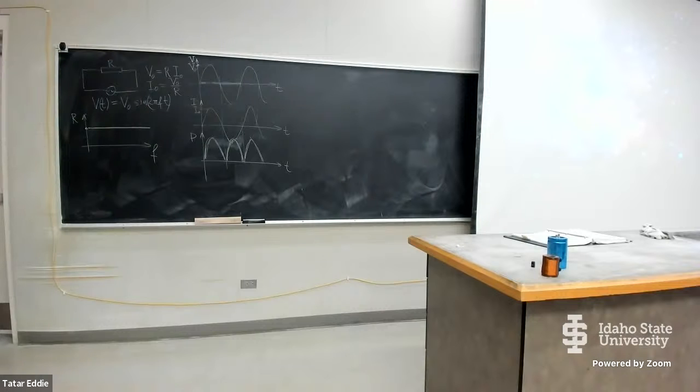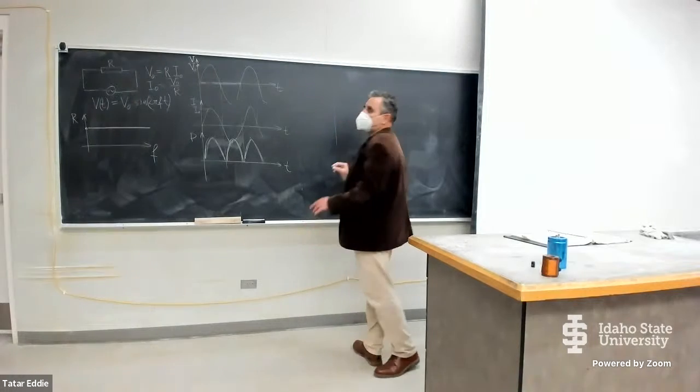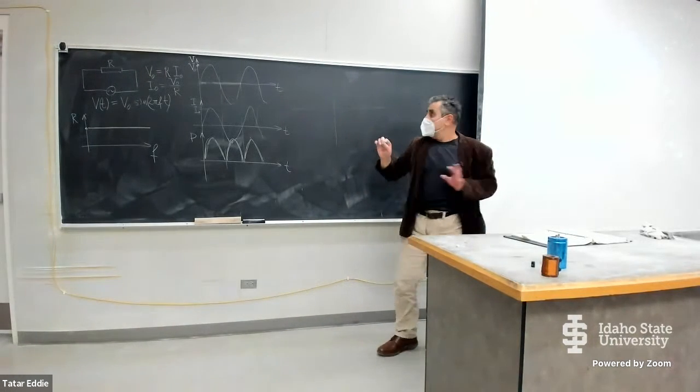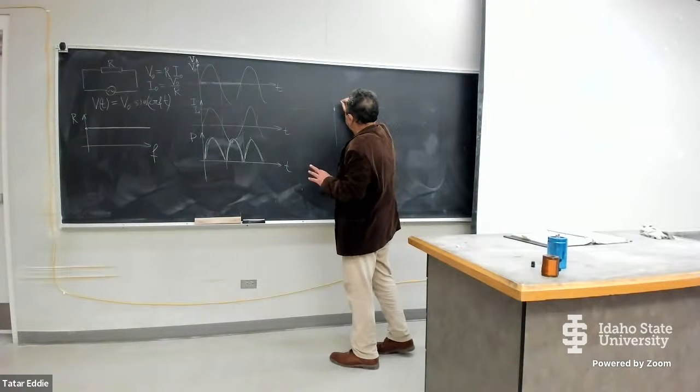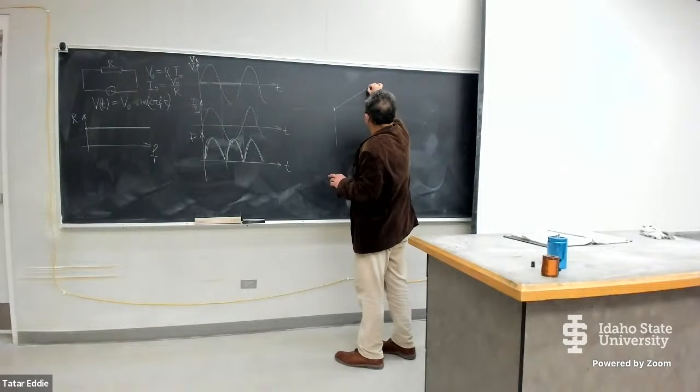And now let's introduce another way of looking at this diagram. Let's represent the value of the voltage with the so-called phasor. So look, I'm just going to have two perpendicular lines, no directions, no zero. And I'm going to think about the voltage as a vector, like this.